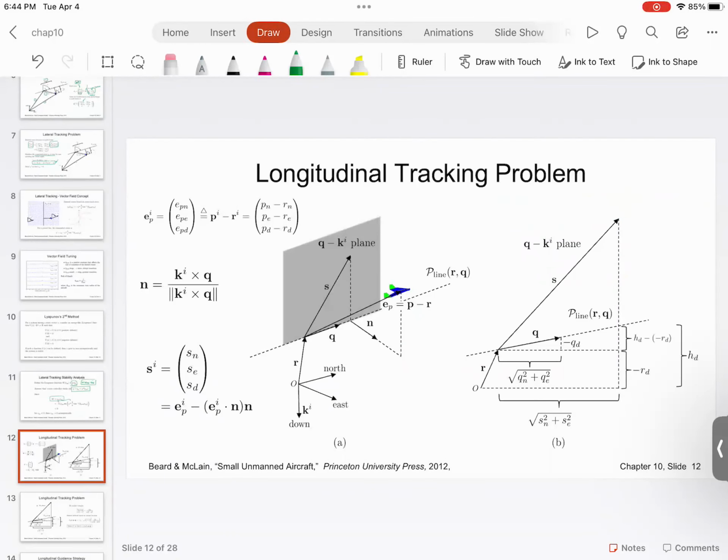What that means is it gives only sufficient conditions, but not necessary conditions, which means if you use a Lyapunov function and it doesn't work out, that does not mean the system is unstable. That means we may not have found the correct Lyapunov function. But if you find a Lyapunov function whose derivative is negative definite, then you can say for sure the system is stable.